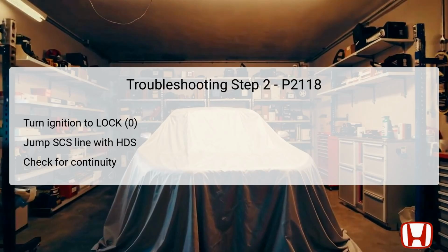The next action is to check for continuity between specified test points in the wiring. Ensure continuity exists between the gray wire at the ECM connector C, pin number 14, and the gray wire at the throttle body 6P connector, pin number 3. If continuity is present, this confirms that the SG3 wire is functioning properly, necessitating a move to step 3. However, if testing shows no continuity, this indicates an open circuit issue, requiring repair of the SG3 wire before rechecking the system.